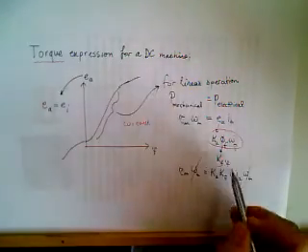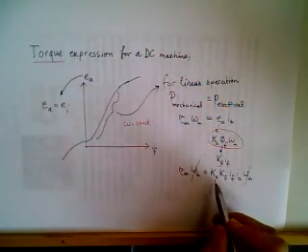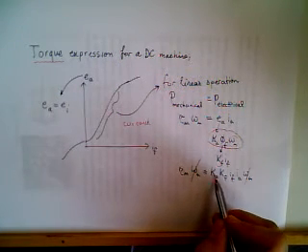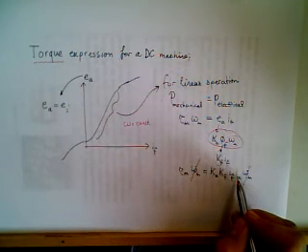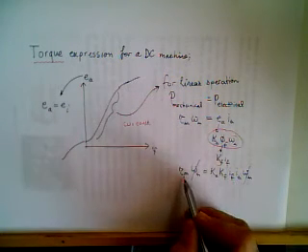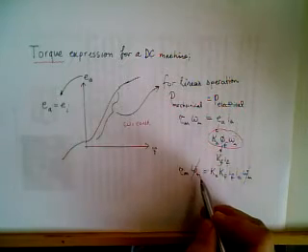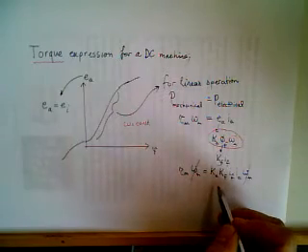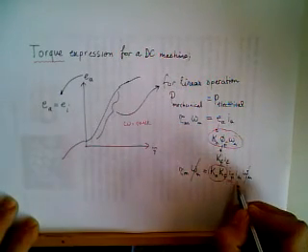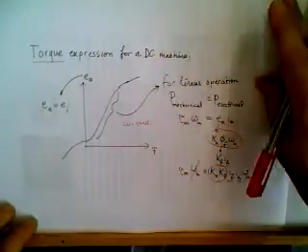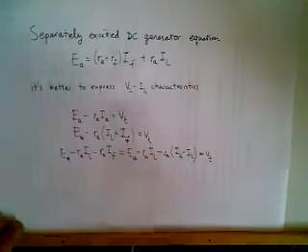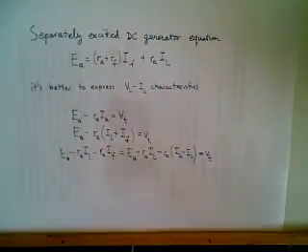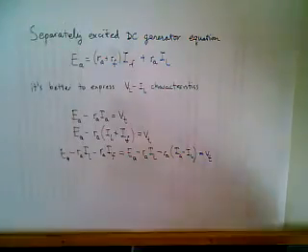When we replace this into the equation above, we have two K constants in omega times field and armature currents, and the rotational speed cancels out on both sides. So we have a torque expression: a constant times the multiplication of two currents, field current and armature current. So this is an important outcome.